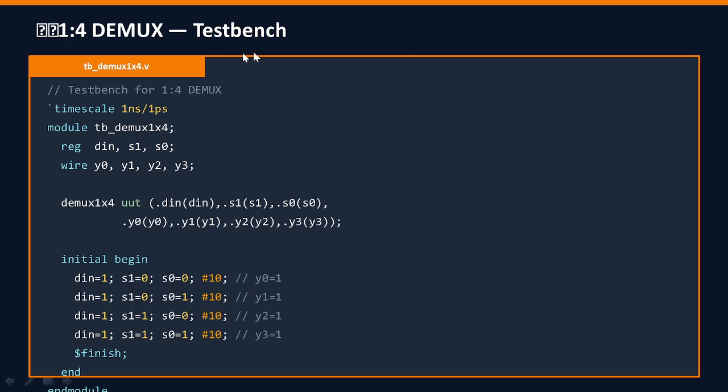Using the same concept, you are going to create a model for a test bench. Mention the ports, naming them as reg and wire. If you have inputs, mention them as reg, and outputs as wire. You are creating a unit under test, using port mapping. Why? Because you are mapping design inputs to test bench inputs. After that you begin the test case using initial begin. After beginning, you are going to test the outputs.